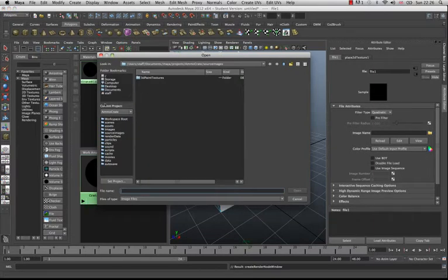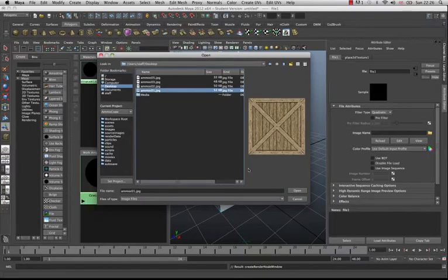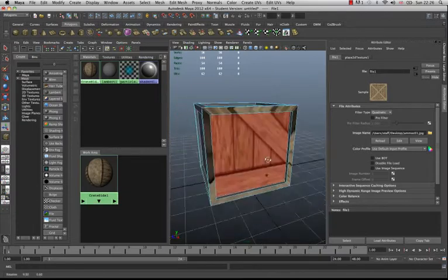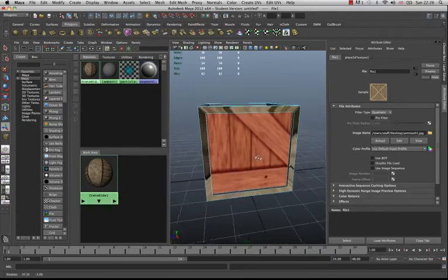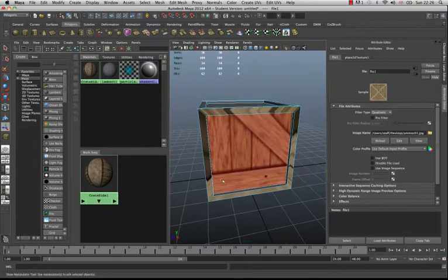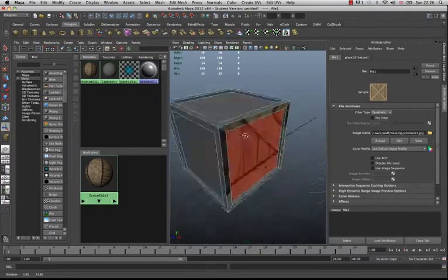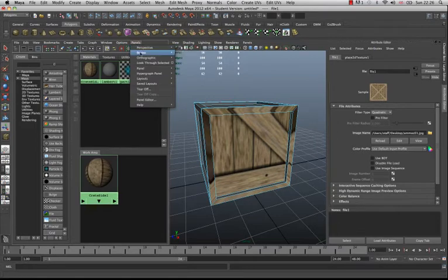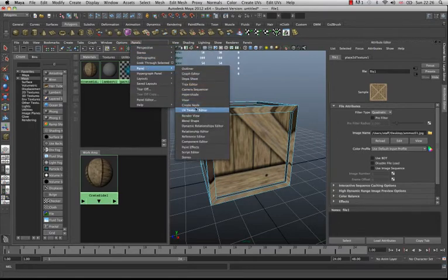And we're going to go choose the file, and the file is on the desktop. So I just go onto the desktop, and I'm just going to choose ammo1 and click open. And there we go. And it looks terrible. And the reason it looks terrible is because of the UV map that is being projected onto this crate. So let's go find, with the panels window, and go down to panel, the UV texture editor.